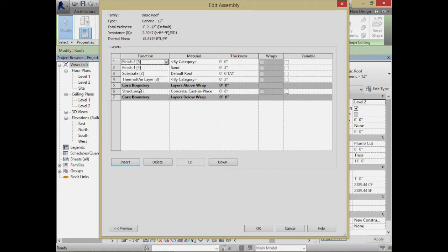Now, as I'm putting in the layers, just so you know, there is some sort of a hierarchy to this. That number that's there has to do with around corners, how things will match with each other, and if things are overlapping, what will come together the best. Finishes that have a 5 will try to match the hardest, and things that have a lower number are considered subordinate in terms of the matching order. So things like gypboard, which need to wrap around the wall, tend to have a very high number. Often your structural layer, things on the inside, have a very low number because they probably don't go wrapping around the outside of the finished layers. So it's an indication of how close you are to the outside, basically.